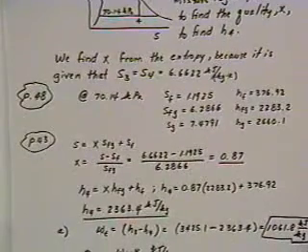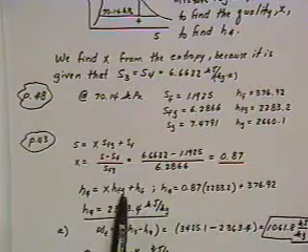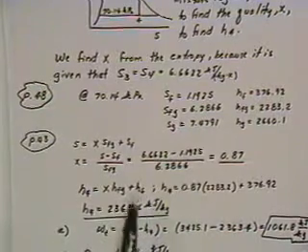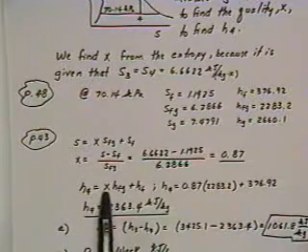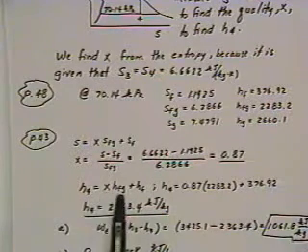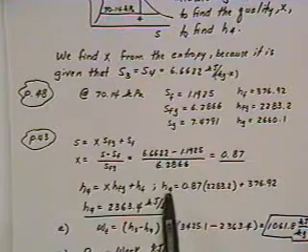Okay, so we could use H4 then is equal to X times HFG plus HF, or the enthalpy at state 4 is found from the quality at state 4, which we just determined, HFG and HF, and so we plug in the numbers, plug in the expression for enthalpy.